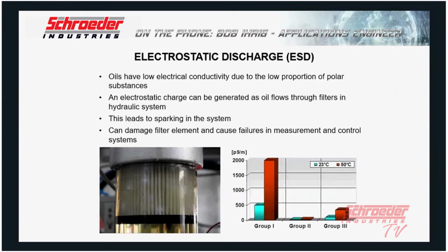Group 3s are also highly refined, as well as group 4s, but due to the typical additive packages, or the lack of additives that are in many group 2 base oils, the conductivity tends to be lower and therefore there is a higher chance of electrostatic discharge.